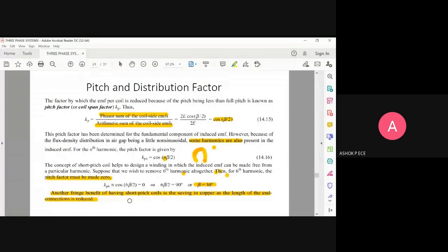See, these harmonics we say here are not required, but in electronics and communication in higher semesters, these harmonics will be required in one application. So the same harmonic is not required in one place, but in another place it is required. It depends on how you use it in your application. For our induction motor, these harmonics are not required. These harmonics will induce noise into my motor. So I want to keep my system free from noise, so I want to eliminate harmonics here.